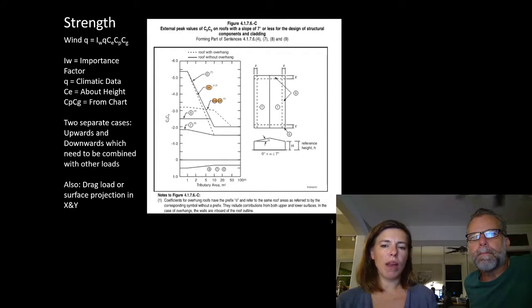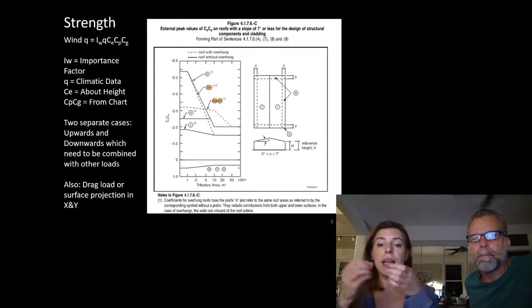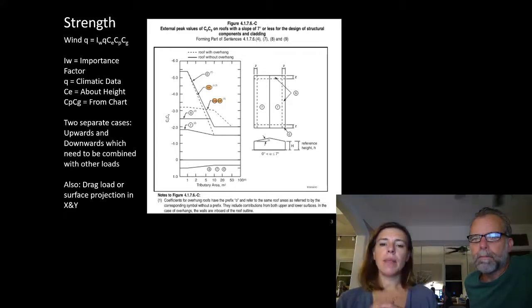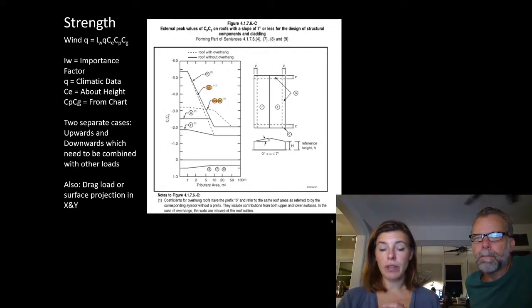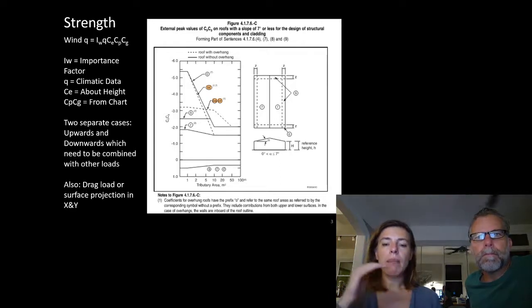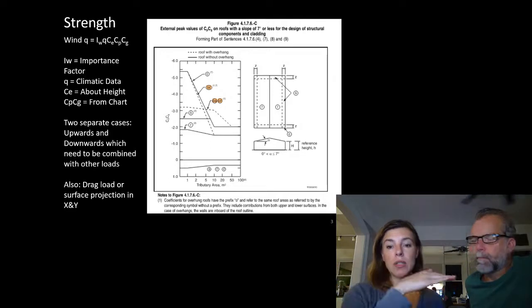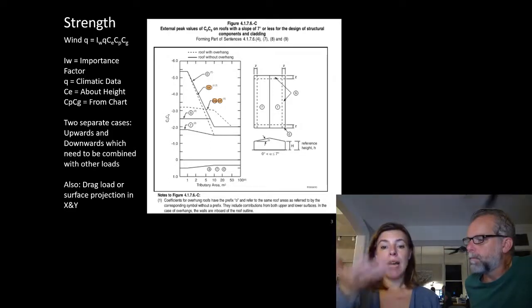Sometimes that seems a little bit low for a wind force. Columns have a very specific spot in the code because they are a round element, and they create turbulence. The same way we have the wind wall diagrams for our guards, there is one for things like standalone columns and cables, so we can access what the wind load is on those surfaces. And if I find the projection on the side of my canopy seems a little bit low, I might look at taking a drag force as a percentage of what the up and down force is.